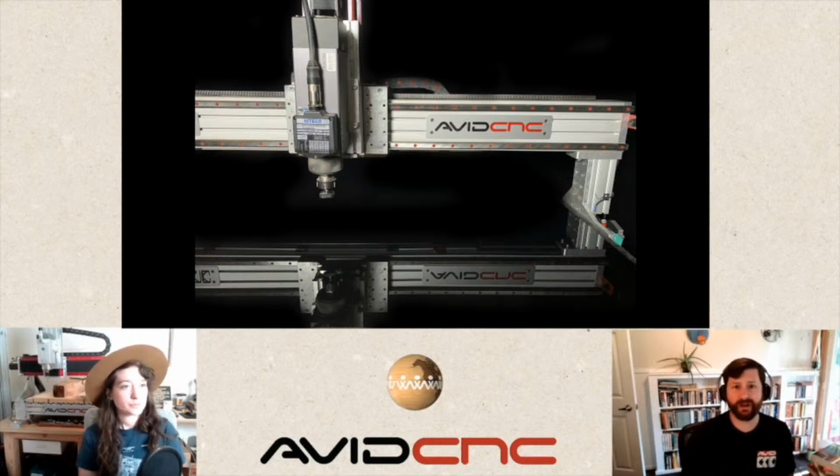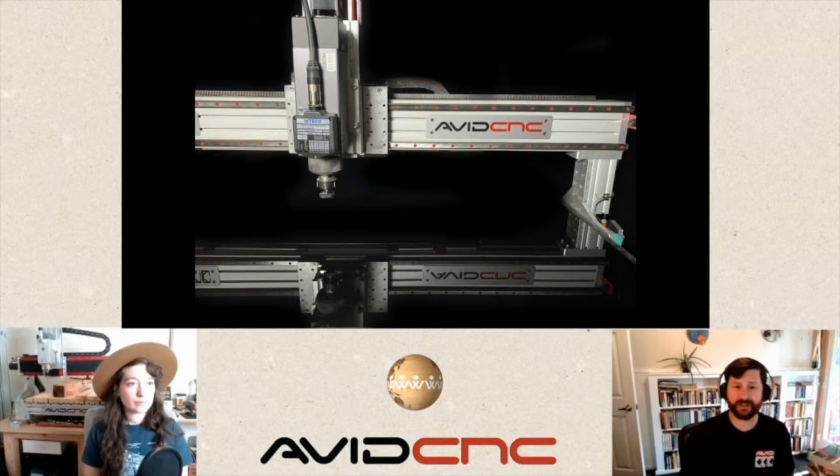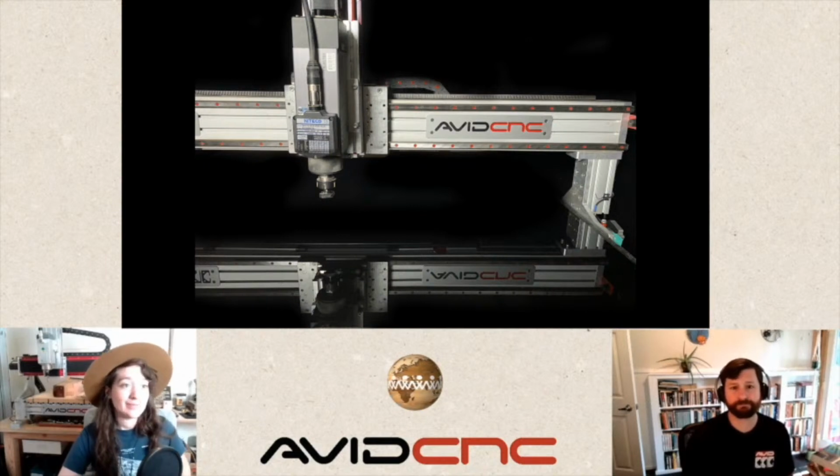And this is one area where I feel a spindle brings a lot of value because of the use of a VFD. We're getting a much less significant drop in power as we reduce our tool RPM. Yeah, definitely, the kind of spindle or router that you have will affect the cut quality.